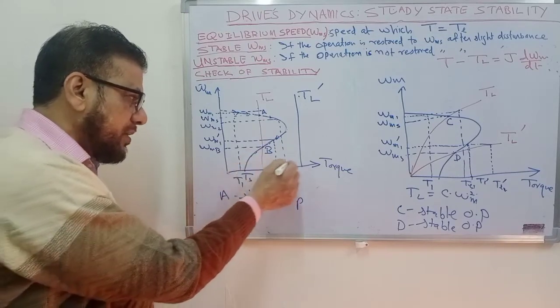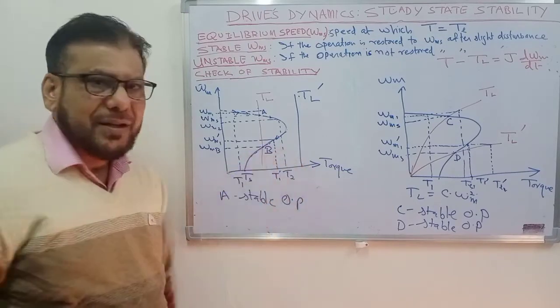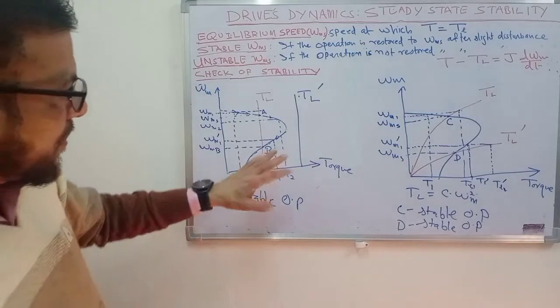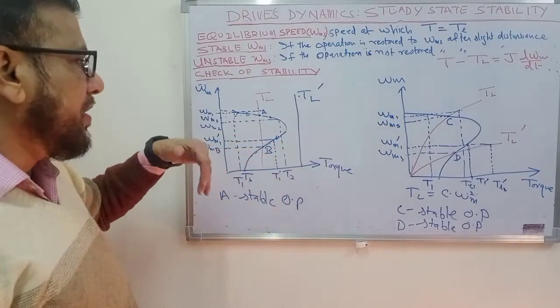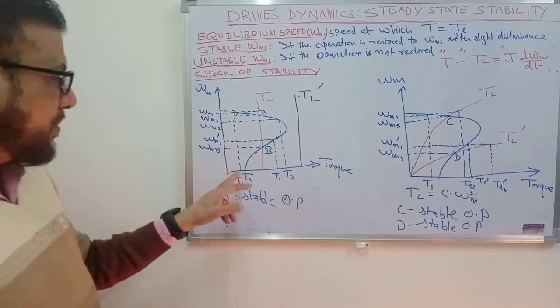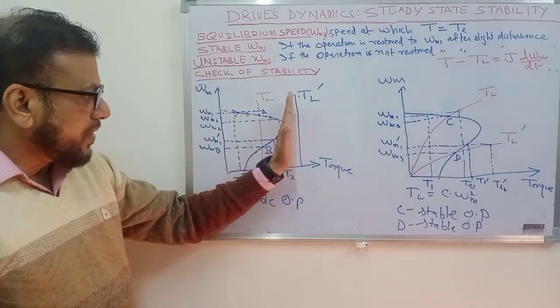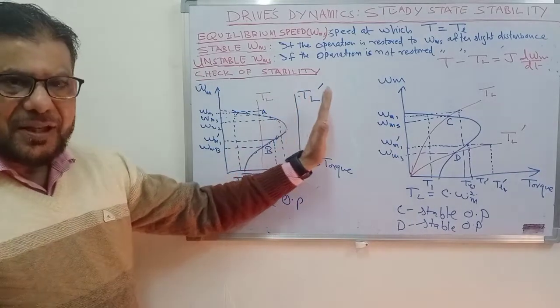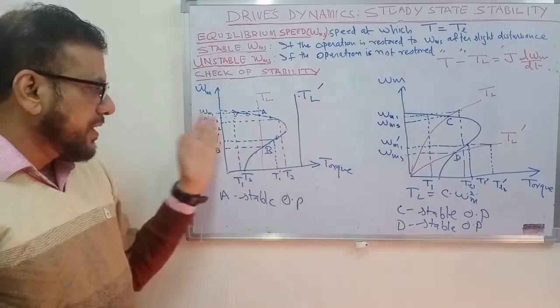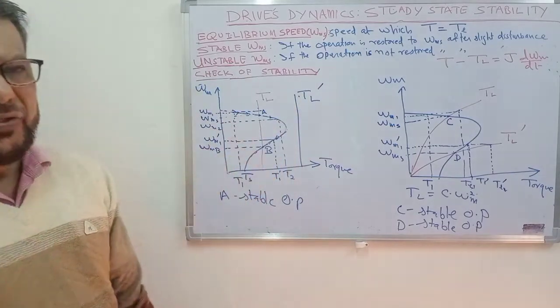Even at zero speed the motor torque is less than the load torque, so the motor will not operate and it will come to standstill.